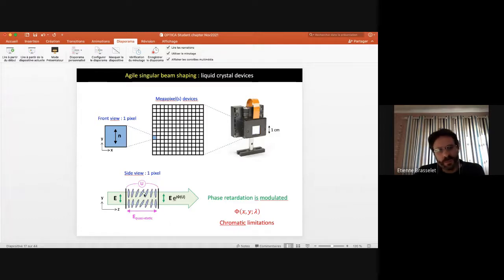And if we apply an electric field for a positive dielectric anisotropy of the liquid crystal, then, as we just showed on the slide before, the molecules will tend to be field-oriented. If the electric field of light is polarized in the plane of reorientation, which is the case in this drawing, it will read this reorientation. And this will be manifested in the phase accumulated as the light passes through the pixels, which means that by varying the voltage between the two substrates in which the liquid crystal is sitting, you will be able to modulate, from one point to another, on demand, the phase of the output light field. So you will be able to shape any phase profile that you want.